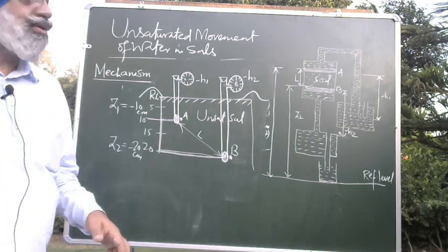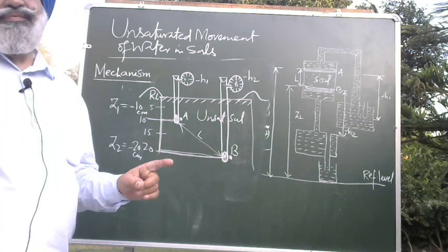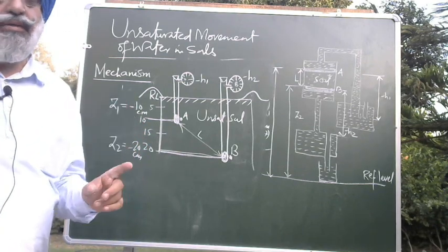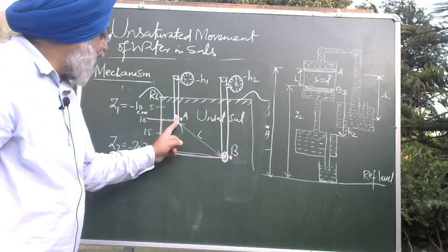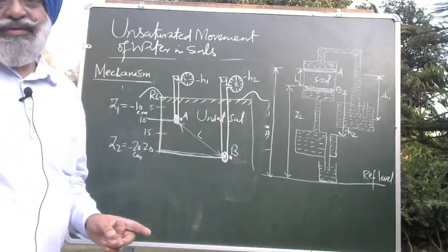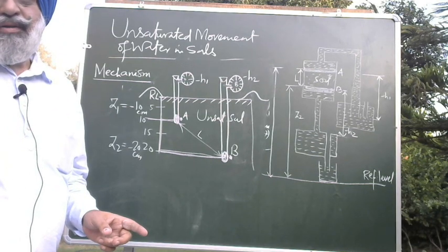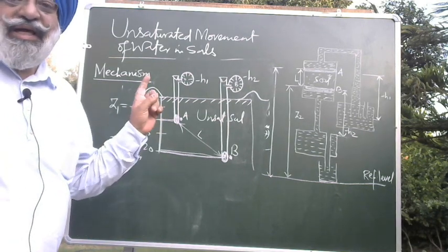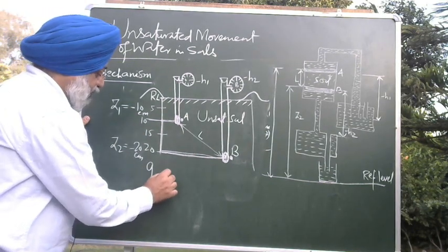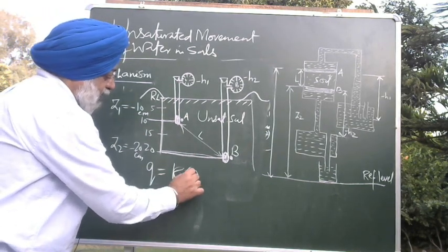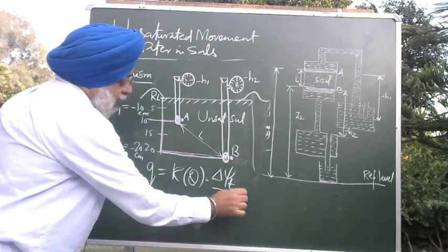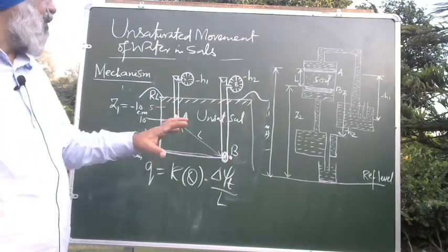Substitute in the equation. Then you have to measure, or rather you should have a record of, the hydraulic conductivity of this layer at a particular moisture content. So this will give you K theta times the total hydraulic gradient. So this is how practically you can do it.